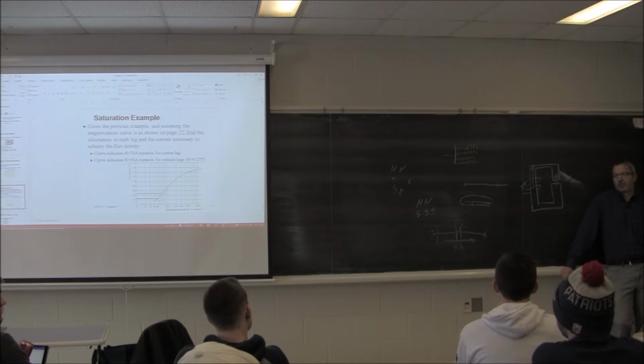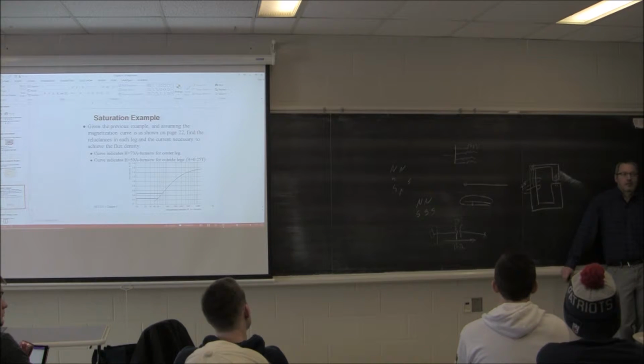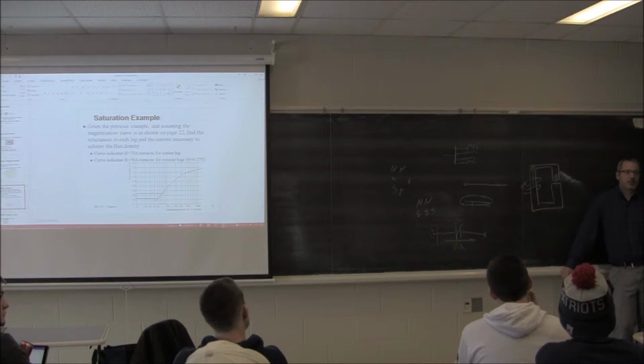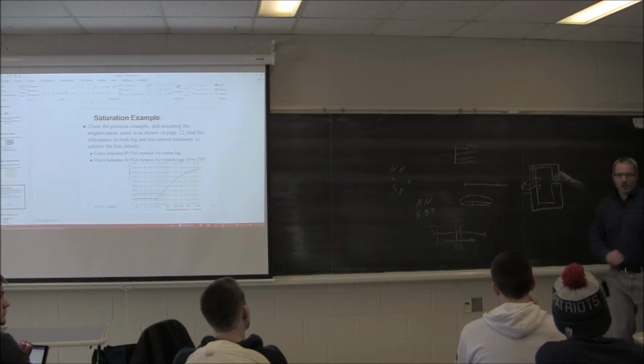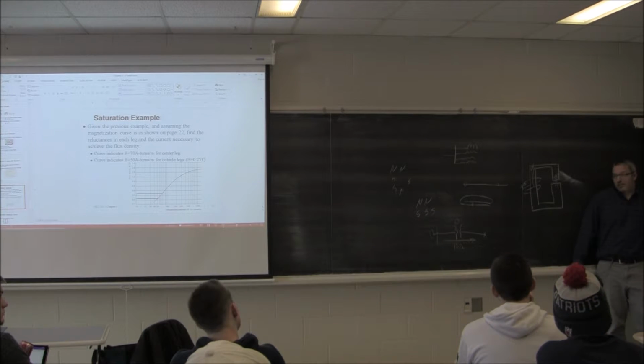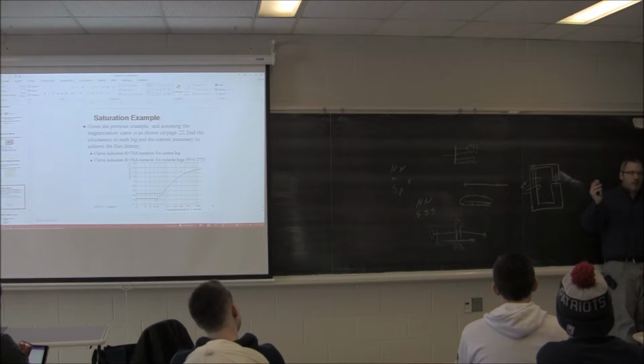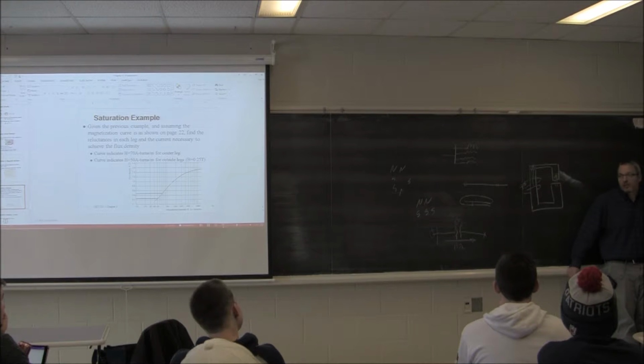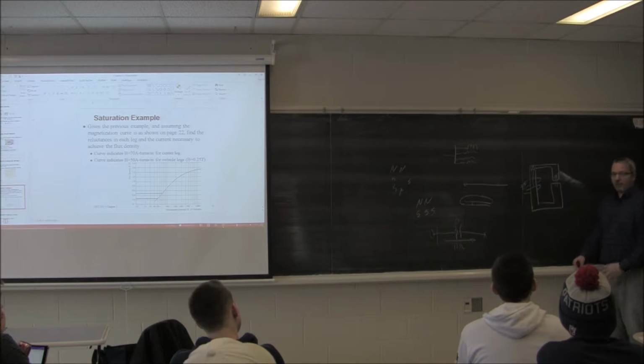All the new stuff though, they put the transformer outside because of fire, right? Because if you have an oil-filled transformer sitting in an electric room, now you've got a fire issue. Even though the oil is really hard to catch on fire. Has anybody here ever tried to start a fire with gasoline? Yes. It just blows up, right? Anybody ever tried motor oil? You start it and it just kind of hangs out, because it just doesn't